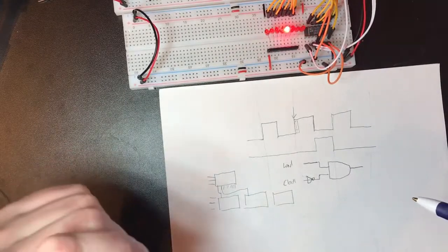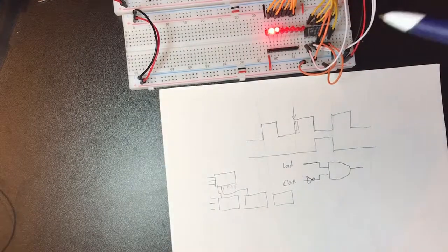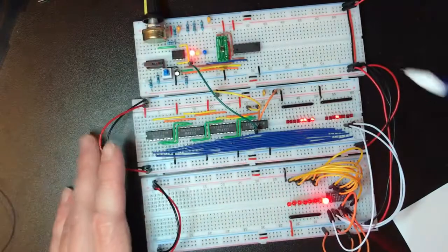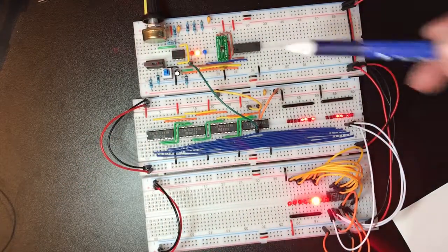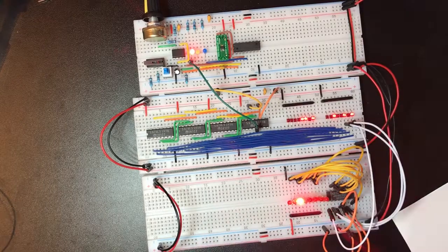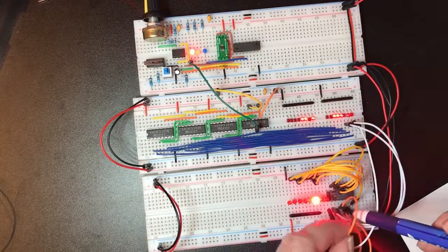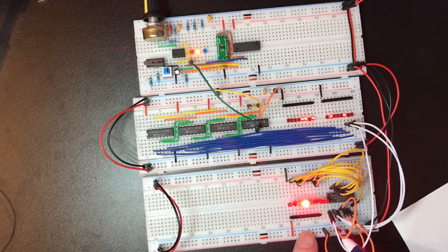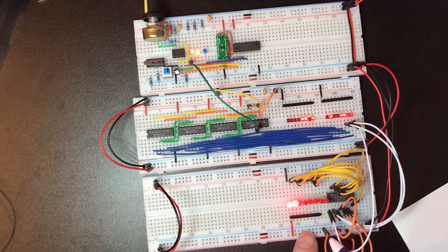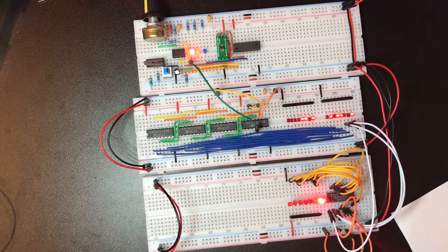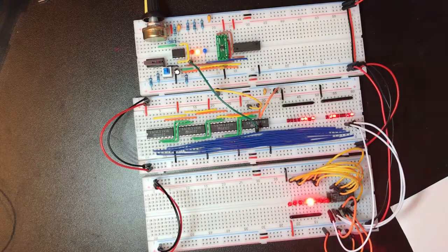So once again, what we could do is grab a spare inverter up here and invert the control inputs, but we've actually got quite an interesting situation down here where 2 of these enable inputs are active low and 1 of them is active high. So if you're thinking about this as I am, we can do something quite interesting and chain 2 of these together without needing any additional chips. So I'm going to drop the wiring for another one in.